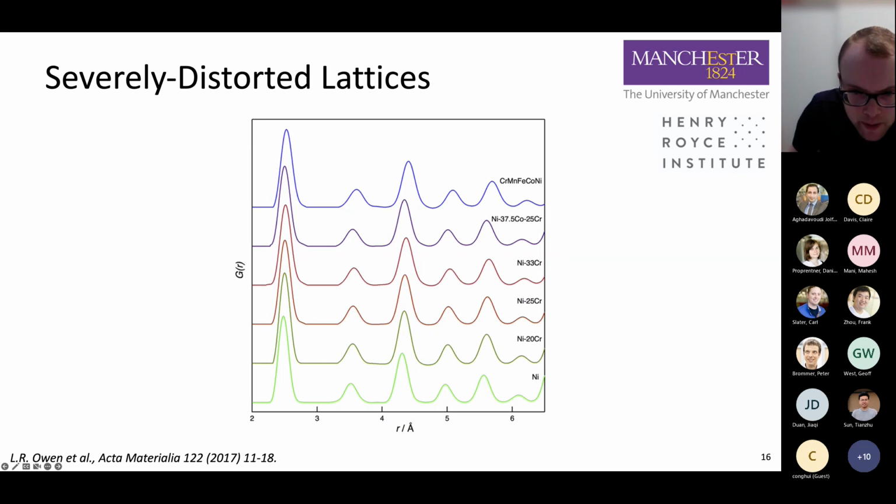And you can see here that if we compare the widths of these peaks, you might be able to convince yourself that the high entropy alloy does have a greater peak width. However, when you account for the fact that the melting point will increase in this direction, and so will decrease down here, in other words this is going to have greater thermal vibrations going on in the structure, the effect really is not a strong one.